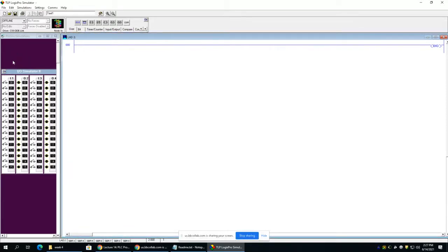Here we have an input module. Notice the I:. The way this address schema works, you have I:1, and then you have O:2, and that's an O, not a 0. So this stands for input module 1, output module 2, input module 3, output module 4. Think of these in pairs. The odd numbers are my input modules, and the even numbers are my output modules.